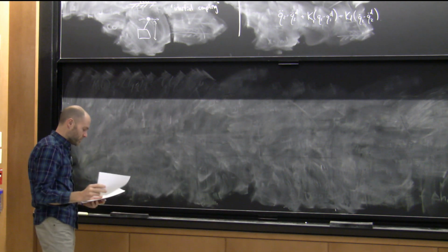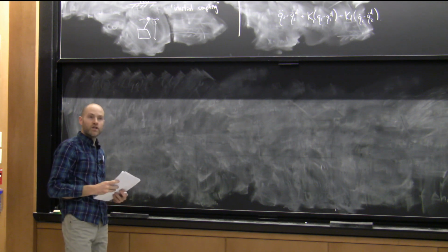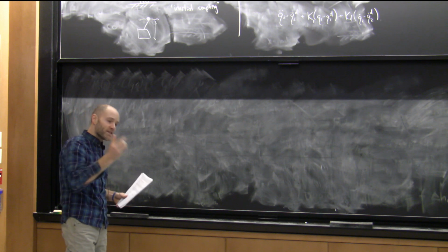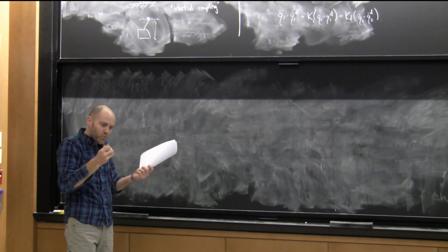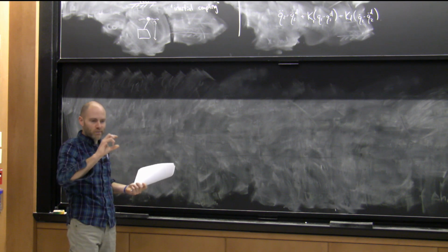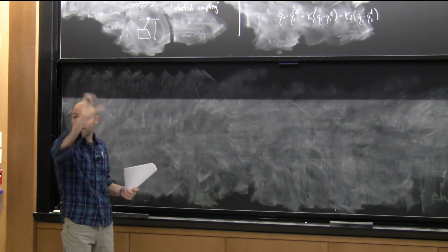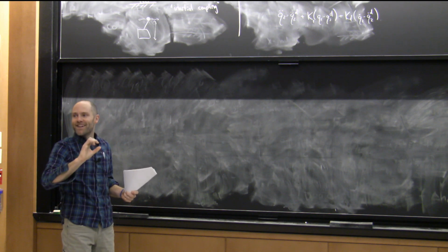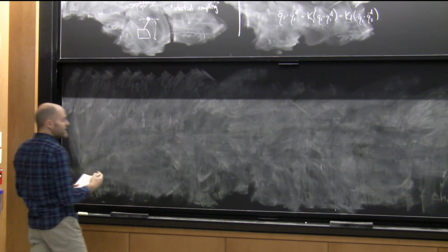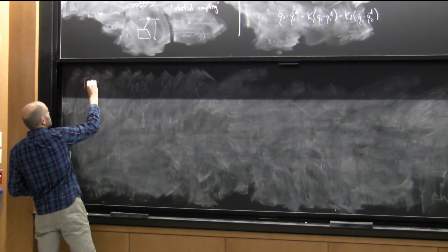The simplest recipe, which is actually quite elegant, is to use the co-located feedback linearization plus Lyapunov. And remember how we did some algebra to make, I saw a k theta, I'm going to multiply that by another theta to make a theta dot squared, and I made all the terms definitely positive. I'm going to do the same thing here, starting with the co-located PFL for the pendulum. So here we go.